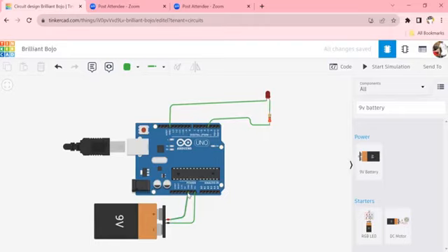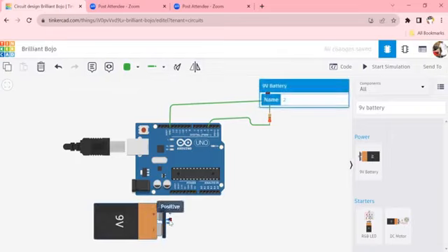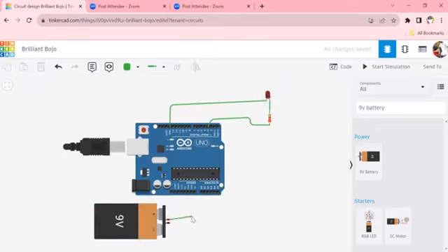Yeah. So click on that wire and press delete on your laptop. Good. Click on the next one and press delete also. Or you can just change it from there. Good. So now draw the red, connect the red or the positive to VIN. Click, click, good. Now connect the next one to GND, the negative to GND.